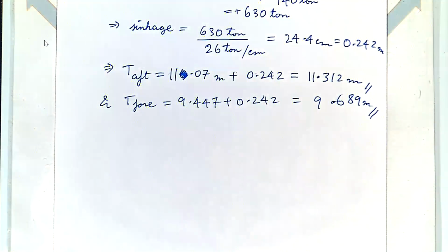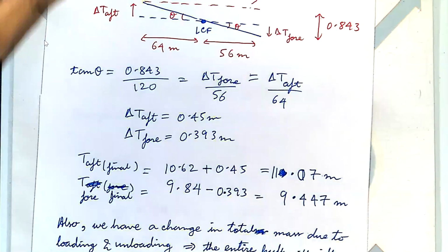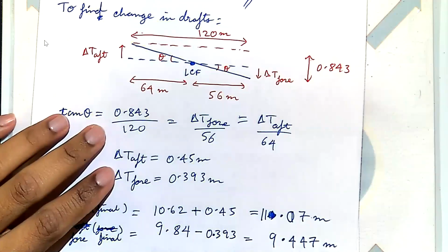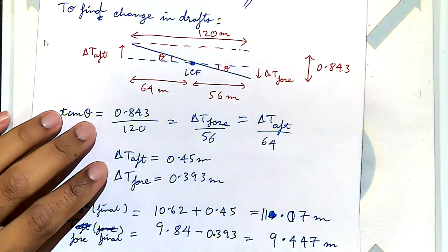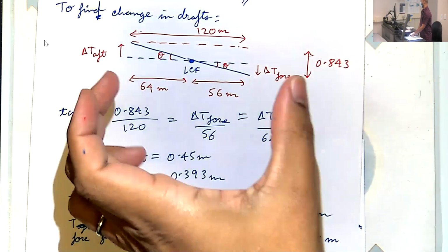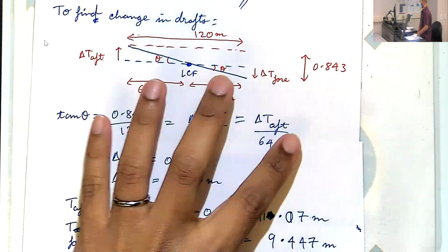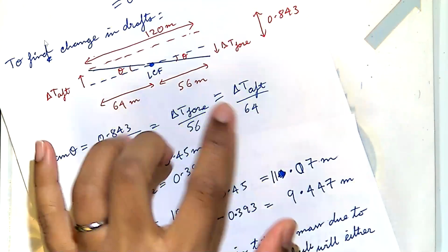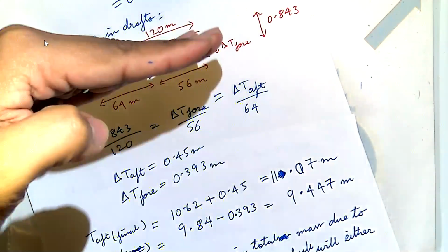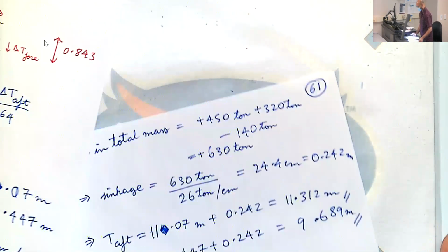Yeah, I have one. So that graph you drew is the water line, right? So you assume that in that visual at least, the ship would stay in the same orientation, your water line's just shifting. For the graph at least. Yeah, exactly. So it is just to make our life easy. The hull on paper remains the same, the water line shifting. But in reality, the water line remains horizontal and the ship would be nose down or up. Okay, perfect. Thank you.